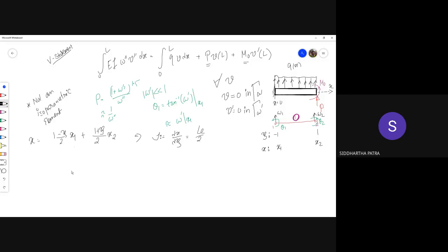But when it comes to mapping the degree of freedom, this is how we represent it using a cubic function. So beam theory uses Hermite polynomial. I'm not writing it because I'm not confident with the spelling itself. But you should look for what type of shape functions beam elements use. So they are Hermite polynomials which are cubic in nature. So basically I should be able to write it as C0 plus C1 xi plus C2 xi squared plus C3 xi cube.